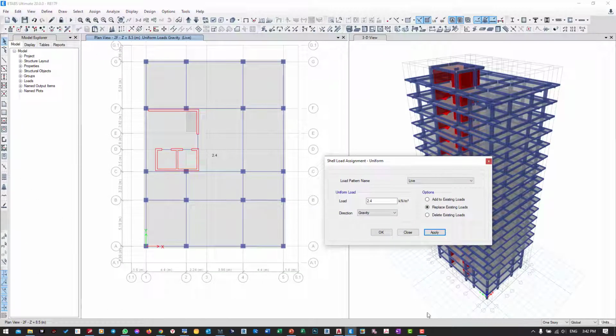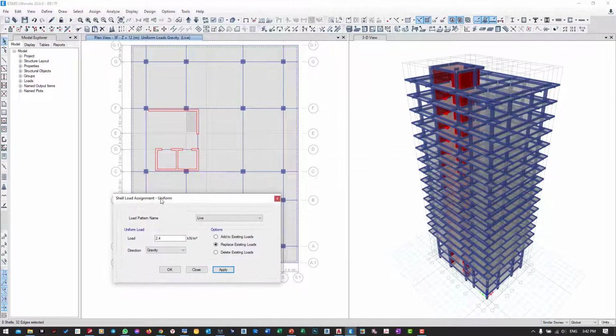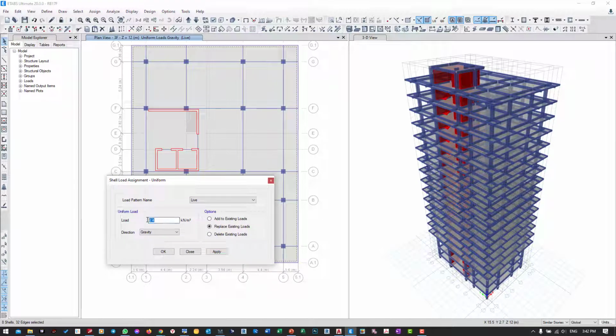From the next we go up to level 3, and I switch to similar story, select all similar story, so the line load should be 1.92 for the residential unit. Apply, select previous, switch to superimposed dead load about 2.42, apply, and the same thing.